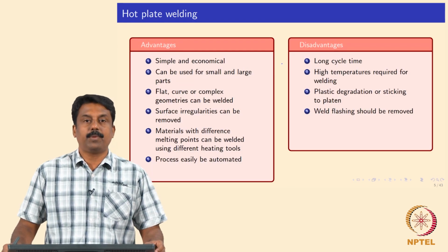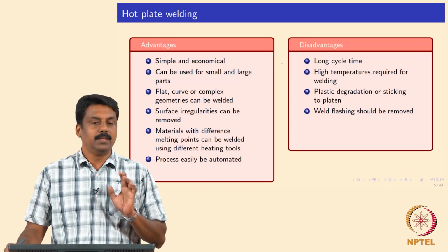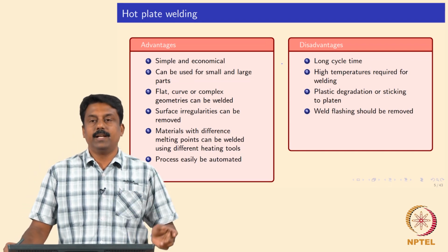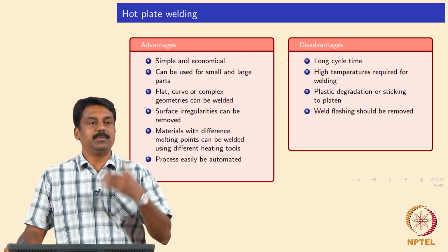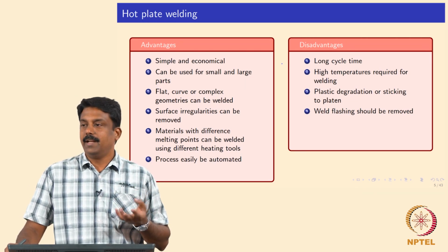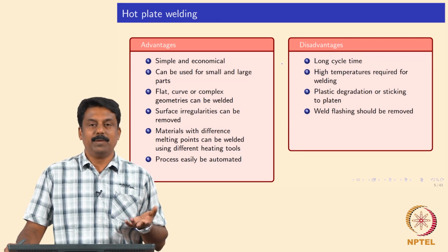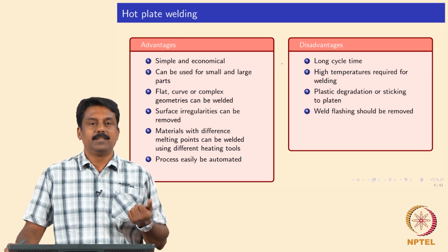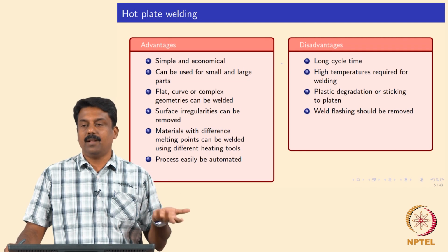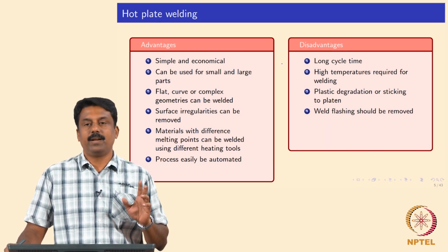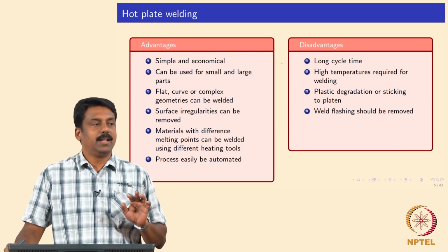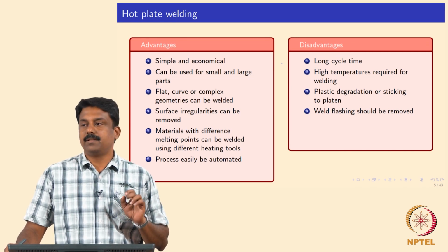So, what are the advantages of this process? It is very simple and very economical. You do not need a really complicated heating mechanism like you see in induction welding, and it is not messy. It can be used to weld large parts or small parts, flat, curved, any complex geometries. And the other important advantage concerns surface irregularities.